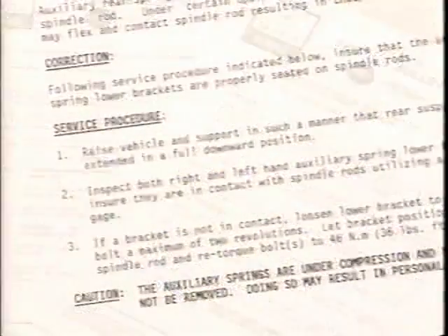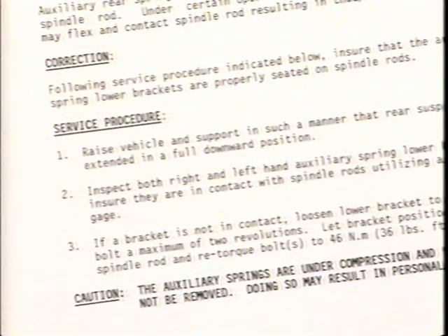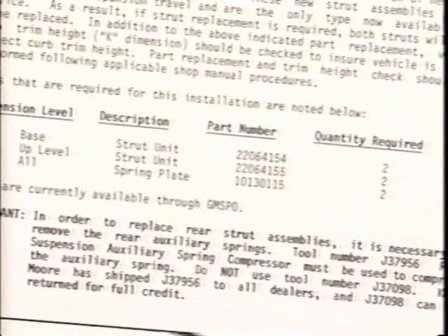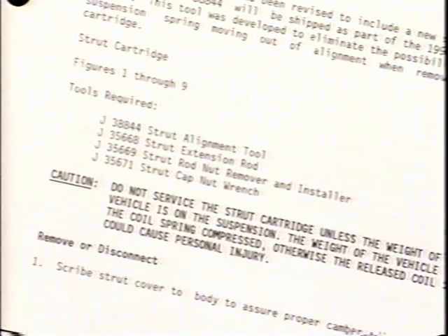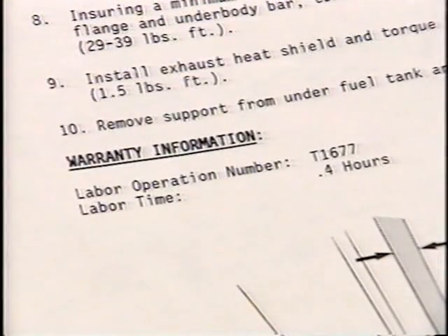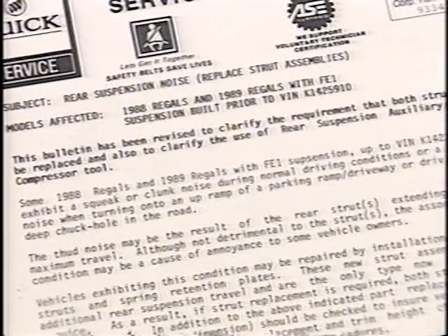Bulletins can save you time by identifying specific repair procedures, service part numbers, special tools required, and appropriate labor operation numbers. Before you perform a service bulletin procedure, be sure the model year and VIN number information corresponds to the vehicle being serviced.